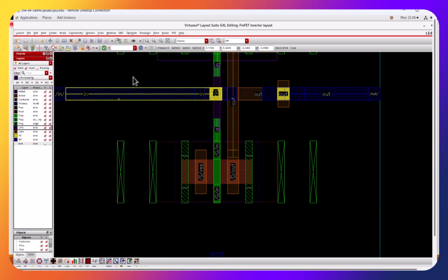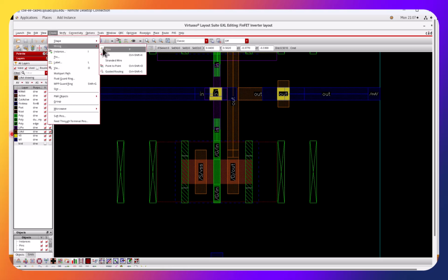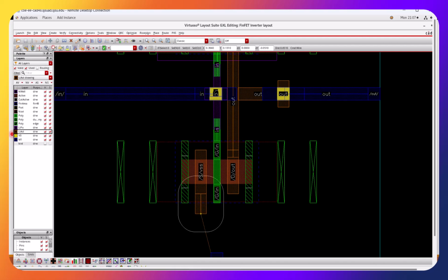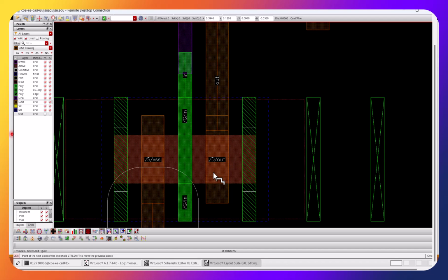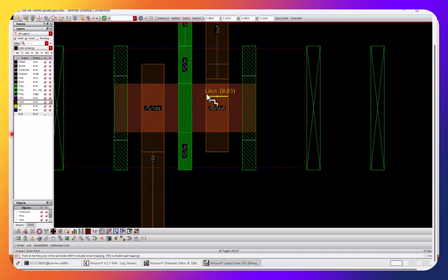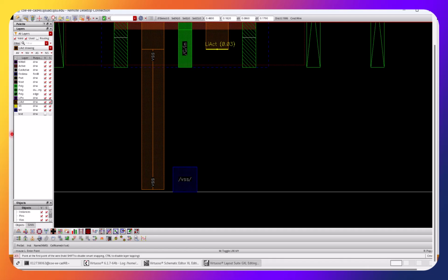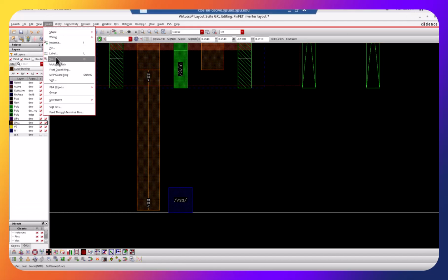So I will do the same thing for the NMOS. I create wire, yeah. We need it to overlap. There will be DRC error later. So, yes, correct. We will talk about N-well later, right? So I just extend this. And then again, I zoom in, I go down. And then what do I add this time? I'm going to say create via.